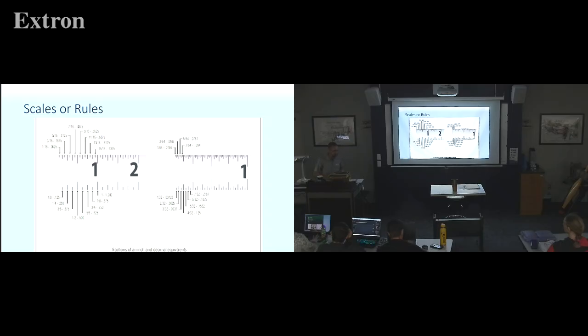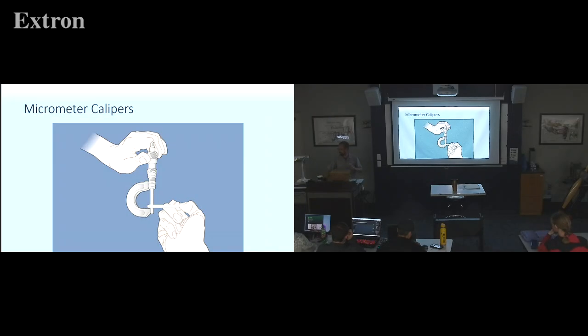All right, I already demonstrated this, so I don't need to show you this here now. Okay, your gauge block or whatever your gauge block is, okay? Those telescoping gauges that I showed you in the top drawer of the toolbox, that's what I'm using a micrometer for. So I'll take the measurement, wham, and then I'll bring it over to the micrometer, and then I'll use this little bitty portion right here to turn it onto that telescoping gauge until it clicks.